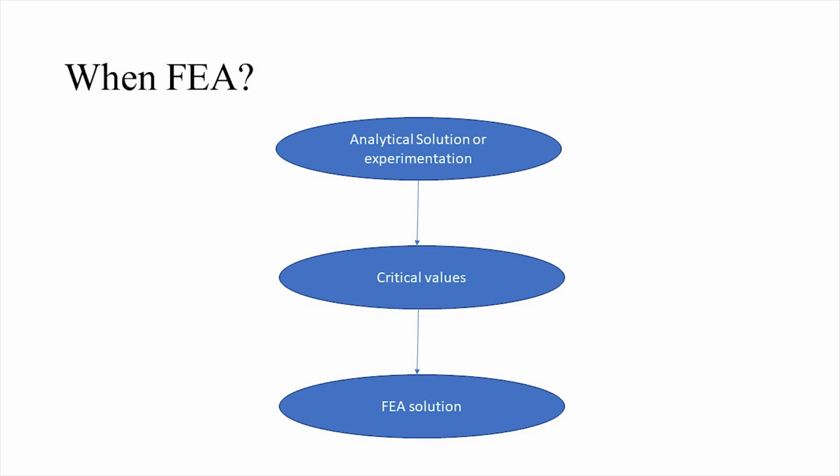So when to use FEA? Most of the problems have solutions which are obtained from correlations based on experiments or some other techniques, and hence may not require an FEA approach. But the same problems under some critical conditions have to be solved using FEA. Example: nozzle design and pressure vessels have ASME standards, but when two nozzles are placed close to each other, they may cross the critical limit, which requires an FEA approach.